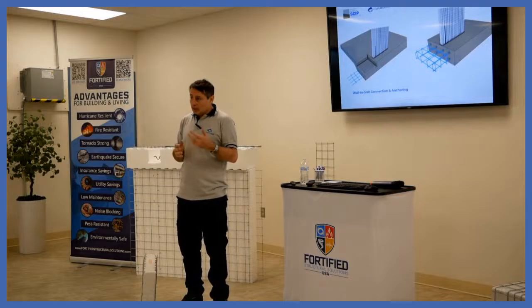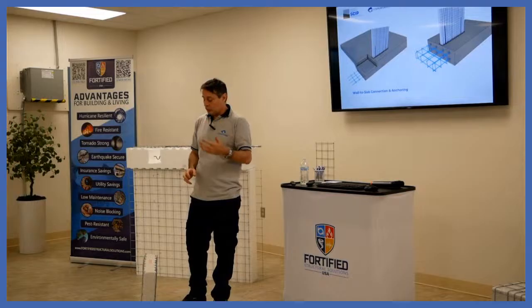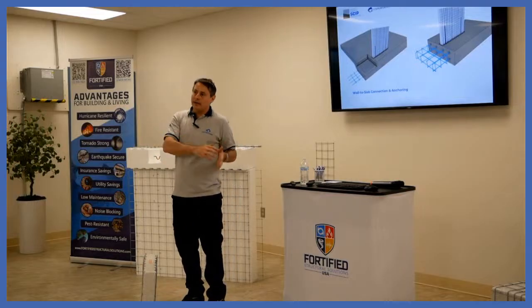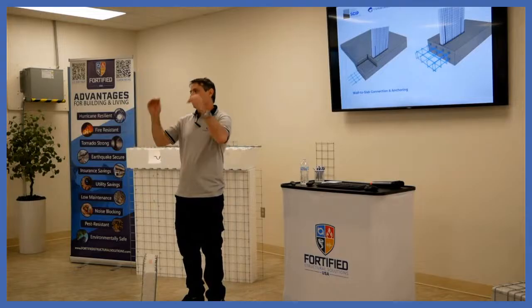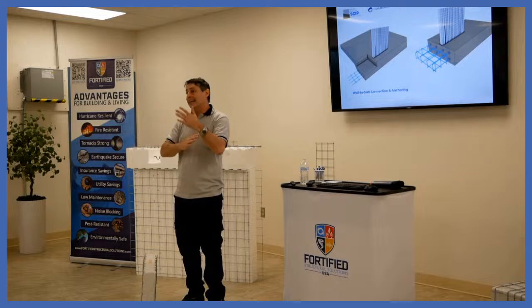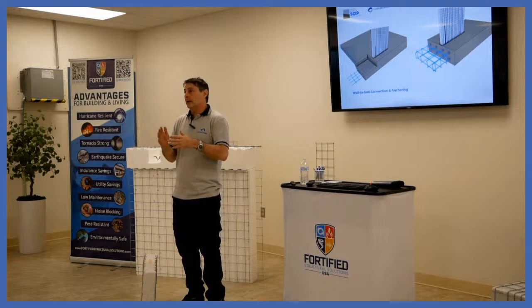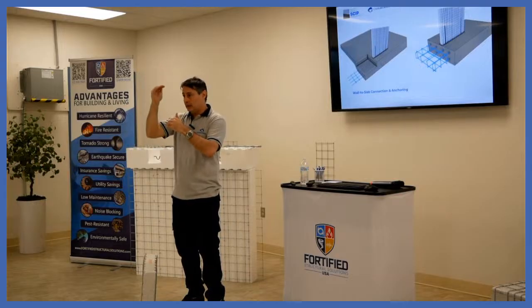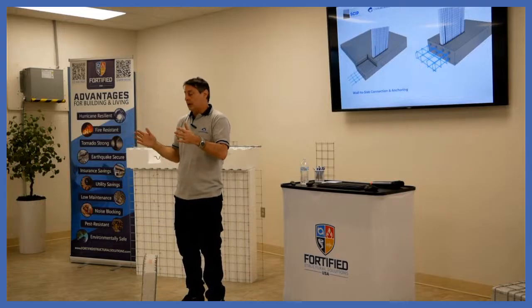For the vertical concentrated load, there's also a table for walls, and those tables apply for the loading capacity and the buckling, and they give you an idea of which panel, the maximum height of the panel, taking into account the thickness.